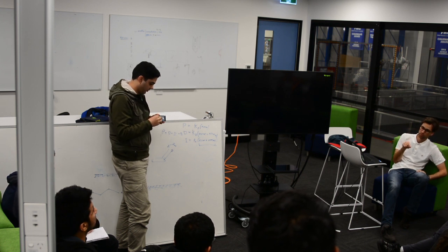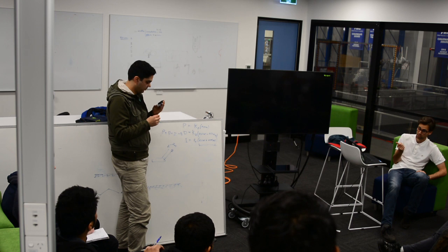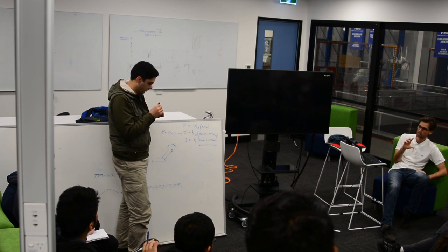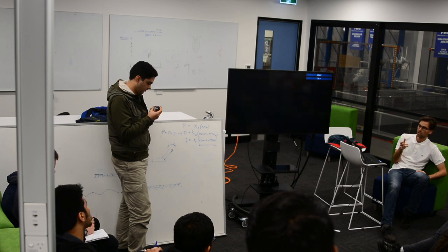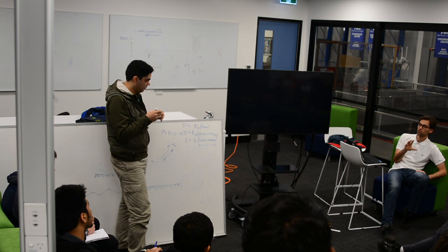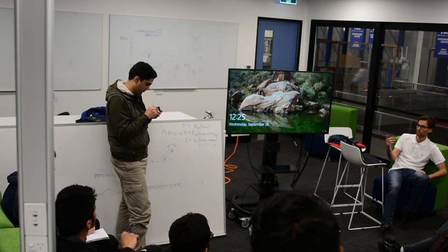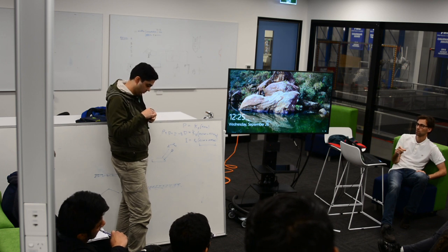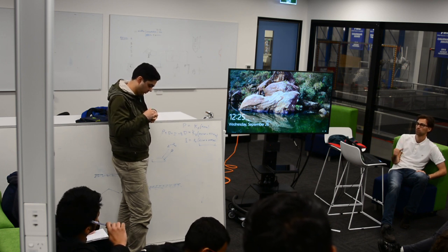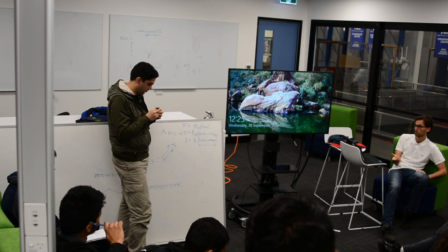And the interrupt service routine's only job is to either increase or decrease the number of counts any time a pulse goes by on the encoders. If you are only ever going to move forwards, never backwards, you could just say any pulse on the encoder should add to the number of counts. You're just counting: pulse went by, increase the count, increase the count. Every time a pulse goes by, we increase the count. That's how we know where we are.